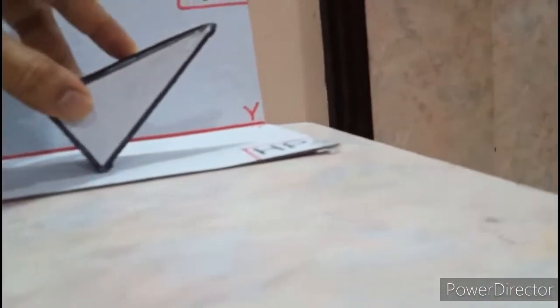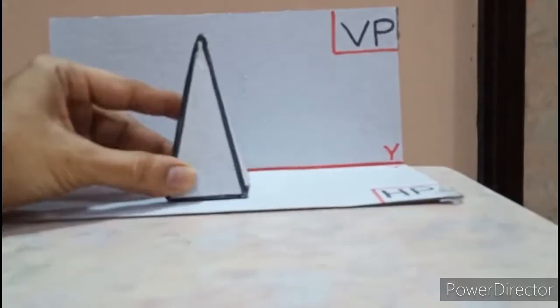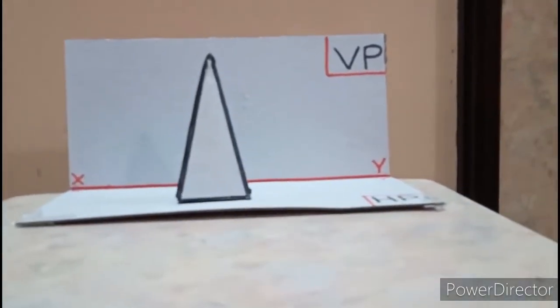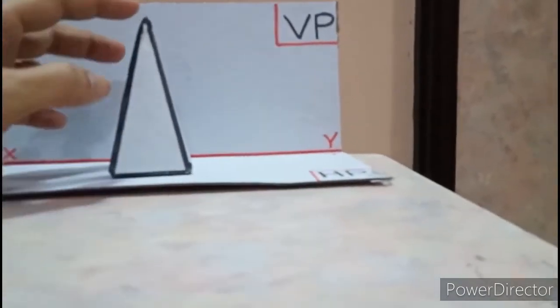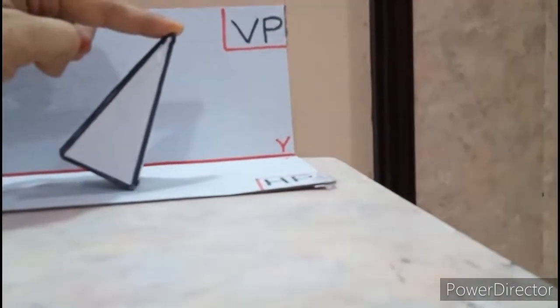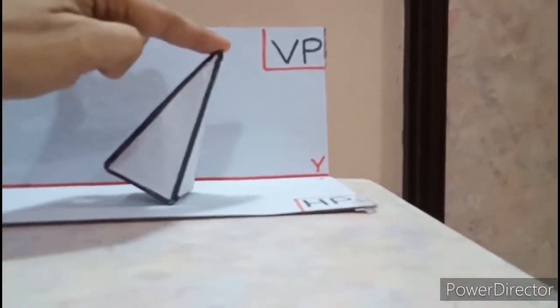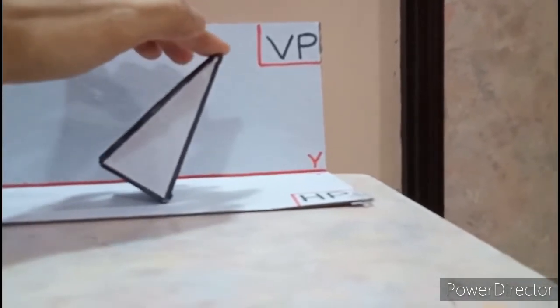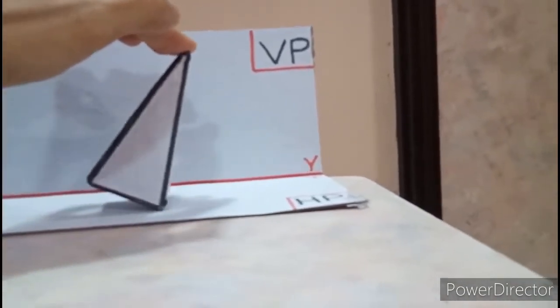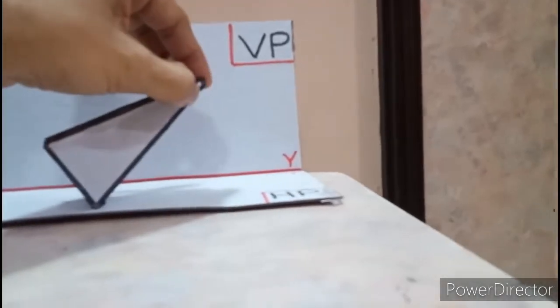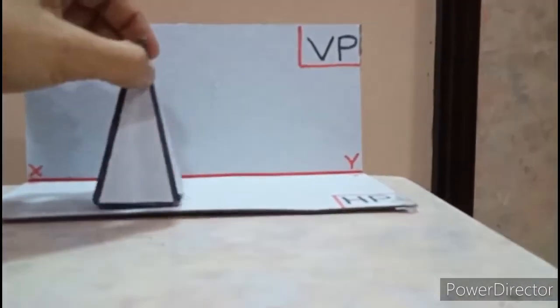You can very well see that the base edge which is resting is AB, but in the front view you can see it as a point. See, it is in air. Now one important thing to realize is, look at the shape and size of the triangle in the first stage. When you tilt this, you will realize that the size and shape don't differ, they remain the same. Only the orientation of the triangle changes. The size, height, length, everything will remain the same. Only the orientation will differ by 30 degrees with horizontal, and that 30 degrees you can see from the front view and not from the top view.